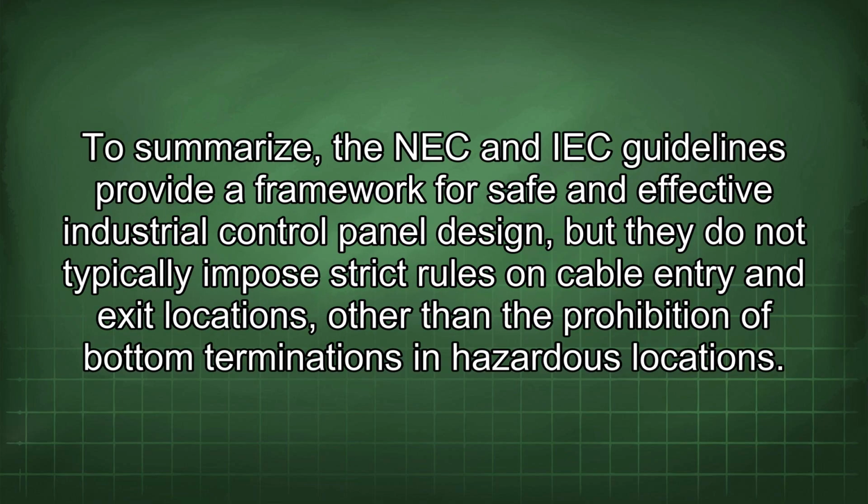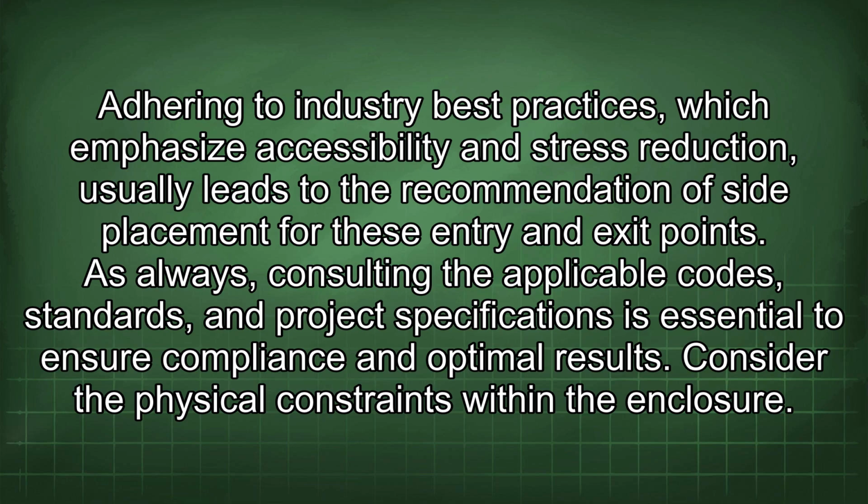To summarize, the NEC and IEC guidelines provide a framework for safe and effective industrial control panel design, but they do not typically impose strict rules on cable entry and exit locations, other than the prohibition of bottom terminations in hazardous locations. Adhering to industry best practices, which emphasize accessibility and stress reduction, usually leads to the recommendation of side placement for these entry and exit points. As always, consulting the applicable codes, standards, and project specifications is essential to ensure compliance and optimal results.